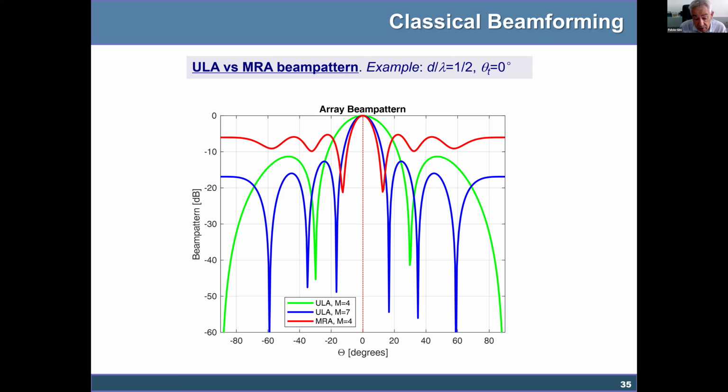And if you use a sparse array, you have some degrees of freedom to choose the trade-off that is good for you. So in other words, by not using a uniform linear array, you can sacrifice a bit of side lobe level, but you can achieve the same resolution because you maintain constant aperture with fewer sensors, so less hardware cost.